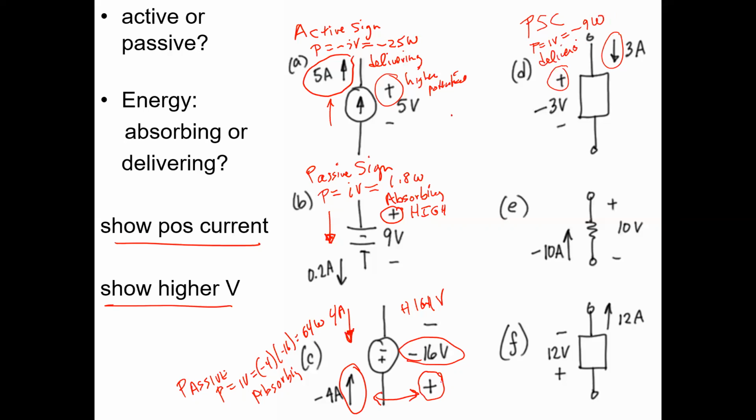And what's the direction of positive current flow? Down. And which side has the higher potential side? Which side has more energy? Yeah, this is the high side. So the current is being impelled to go to a high energy state through that device because it's adding energy to those charges. So it's like a water pump. Another good mechanical analogy of voltage sources, current sources, pumping water. Charge is like the water molecules.